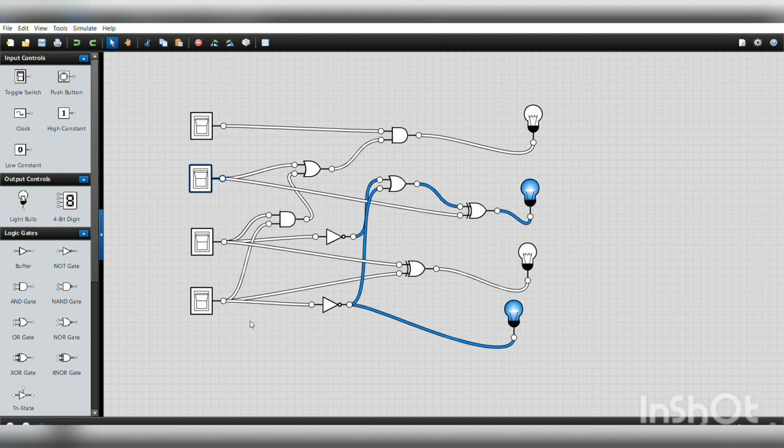So now we are going to see the XS3 to BCD code conversion, out of which your inputs are the XS3 input whereas your corresponding outputs are the BCD output. If at all your input is 0000, your output is 0101. If your input is 0001, your output is 0110. If at all your input is 0100, your output is 0001. And if at all you give some other inputs like 0110, your output is 0011.